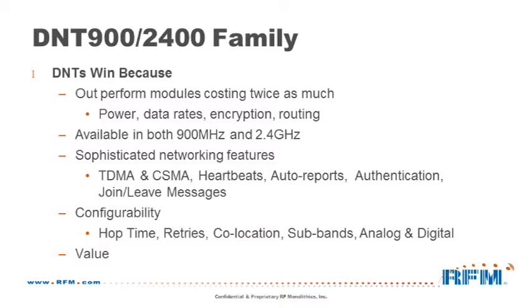We have a TDMA, a time division multiple access scheme, where every remote gets the same amount of bandwidth, and that's limited to 16 remotes. Or this carrier sense multiple access. So this is the listen before talk mode, similar to Ethernet, similar to Wi-Fi. And in this mode, there's no limit to the number of remotes.